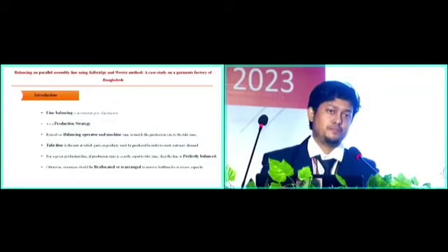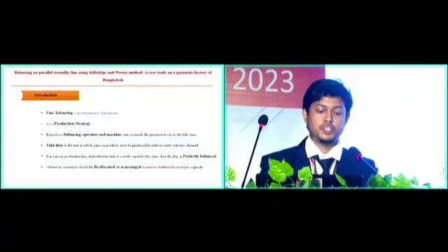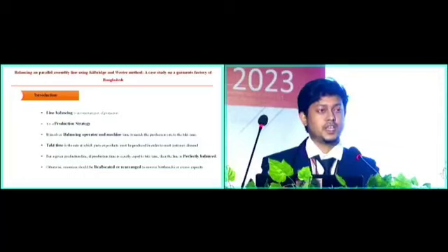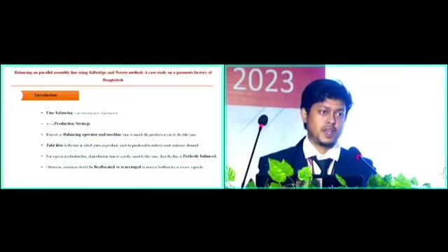What is takt time? Takt time is the rate at which parts or products must be produced in order to meet customer demand. For a given production line, if production time is exactly equal to takt time, then the line is perfectly balanced. Otherwise, resources should be reallocated or rearranged to remove bottlenecks or excess capacity.